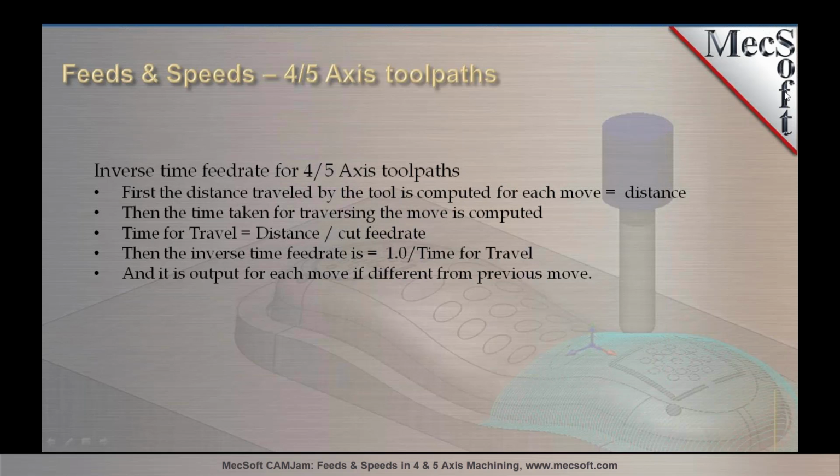Thank you, Krish. So folks, there's two things we're going to talk about. As Krish pointed out in the earlier slide, we'll show you how our feeds and speeds are computed when we use load from file. We'll talk about how it's done using the calculator in here. And then we'll also show you how we use feeds and speeds for our multi-axis motions as well.